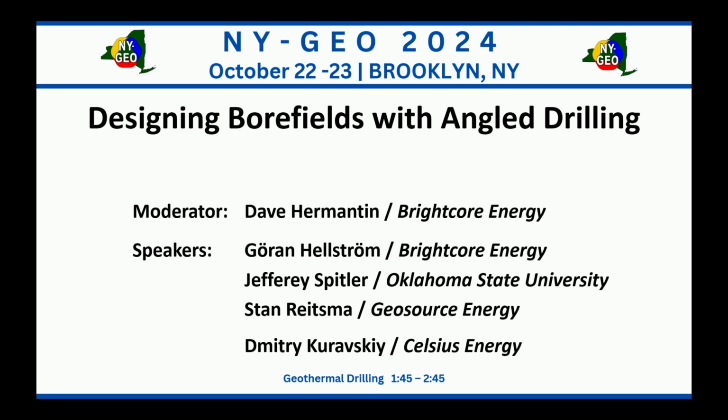Just to give you an example, in drilling, to be able to hold the assembly at an inclined angle, we need to maintain a tolerance of 0.01 inch on the assembly. We got some bits from local manufacturers, and we ordered 6.5 inch bits. The bits came out, some of them 6.4, some of them 6.6. The one which was 6.6 was dropping around 10 degrees every 500 feet. The one which was 6.4 was building 10 degrees every 500 feet. So this is where the cost is coming from.